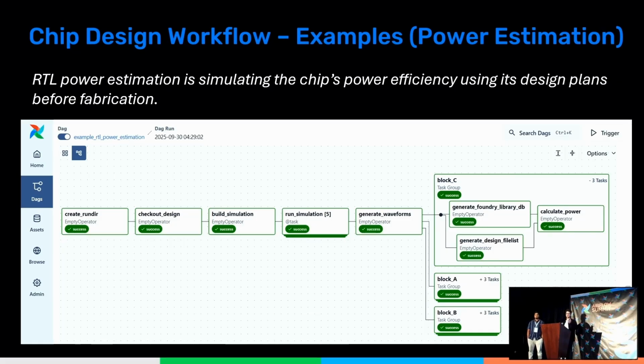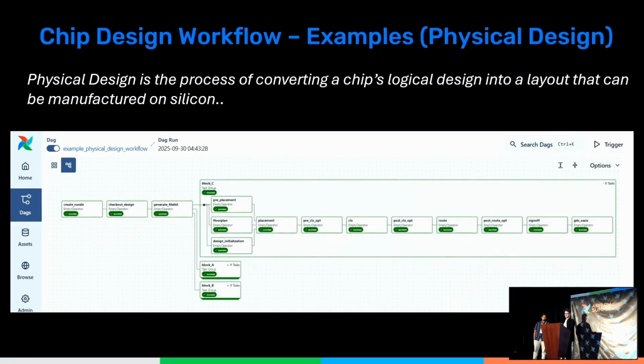The way the power team might actually use this information is to make some inferences and use the actual time series signal values of different pieces of your silicon design to estimate power usage in different operational scenarios. This is really critical information for designing a chip. You need to make sure your design is running within a given power budget, and you're actually able to claim that our chips are really efficient.